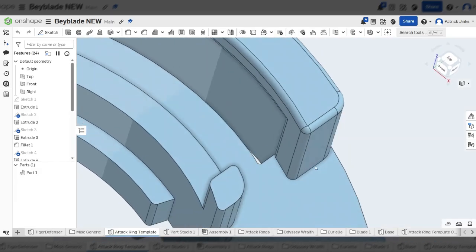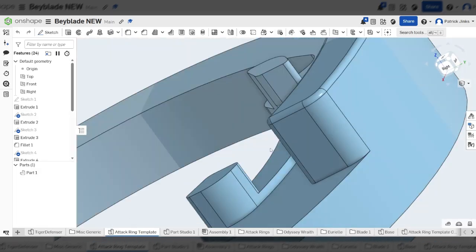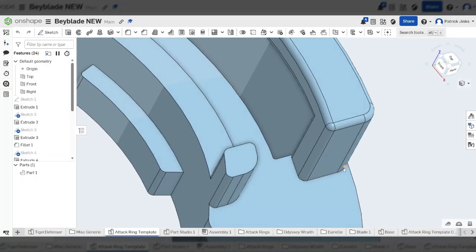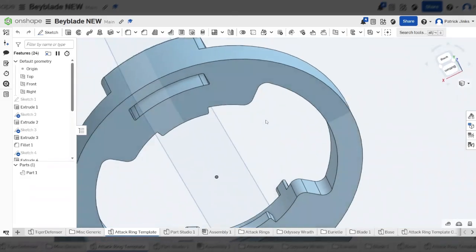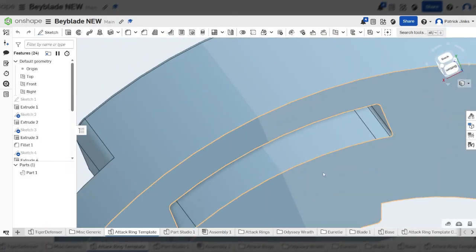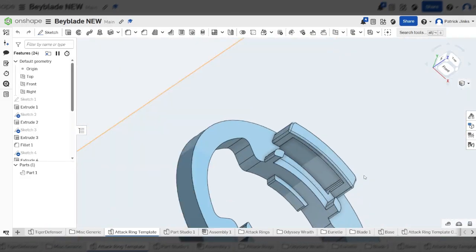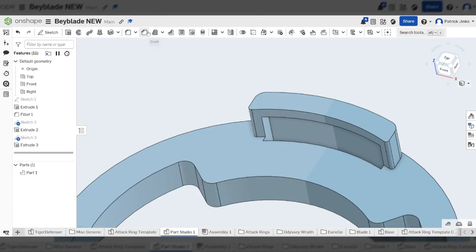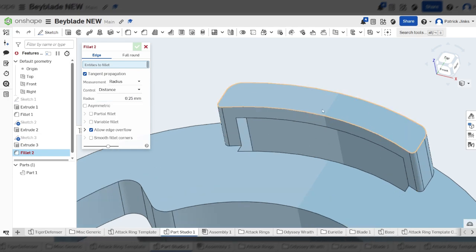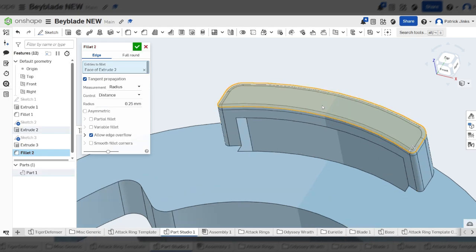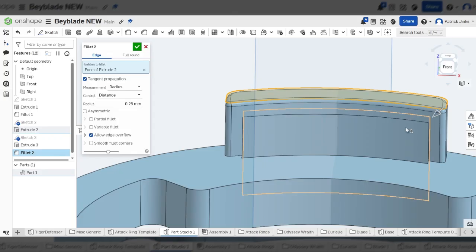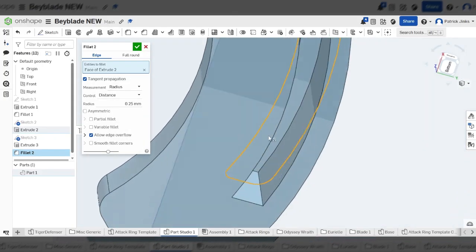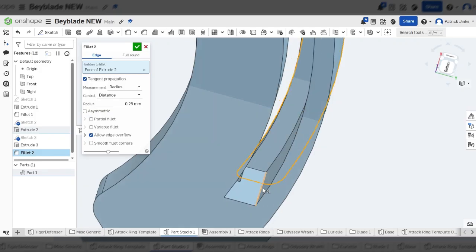Because we're going to add things to that later. So you don't want a fillet round this bottom edge, or at the same time around this bottom edge on the underside. So everything is going to be 0.25 fillet. You can watch through as we do it. Grab the fillet tool, 0.25. I want all my top face, so I can just click that and the fillets will appear. Oh, it's probably easiest to do it this way. I want inside on the edges.